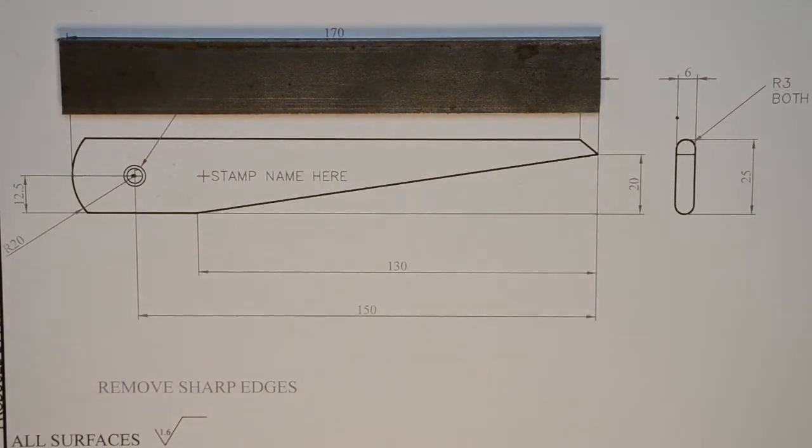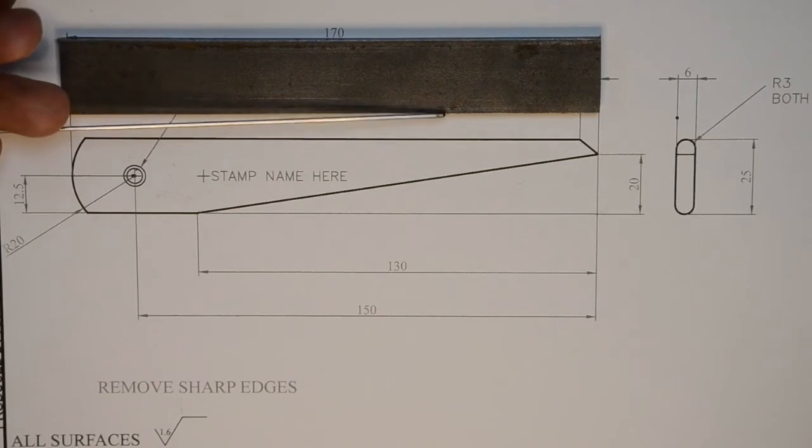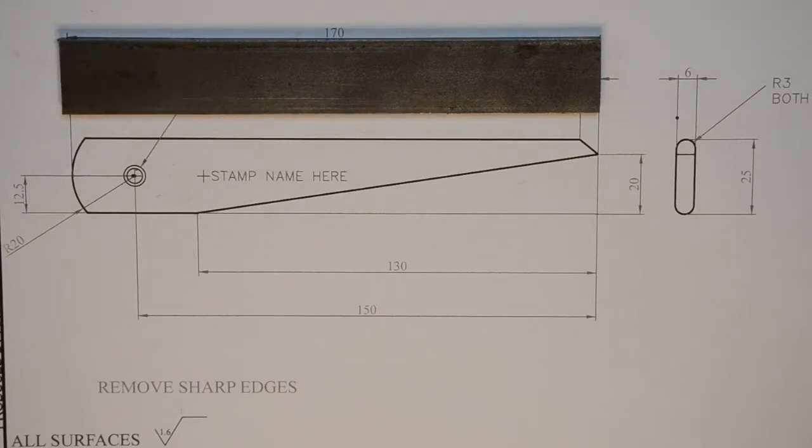So yeah, we might say we've got a nice straight edge here. It's been machined or rolled and supplied to us and it's dead flat. I've checked it on the surface plate. So that's going to form one of our datums. And then we might start filing perhaps over on this edge here to get this perfectly square to that edge and say, right, we've established a datum, we're good to go.